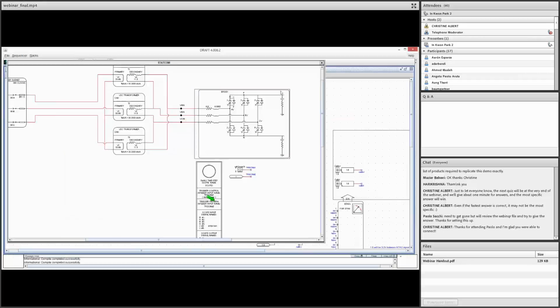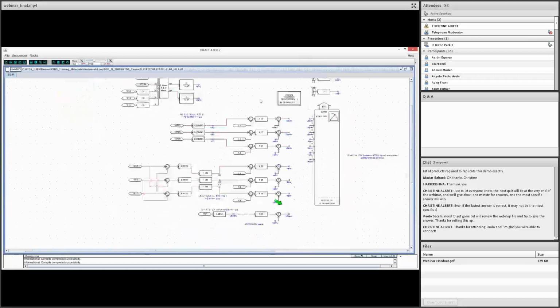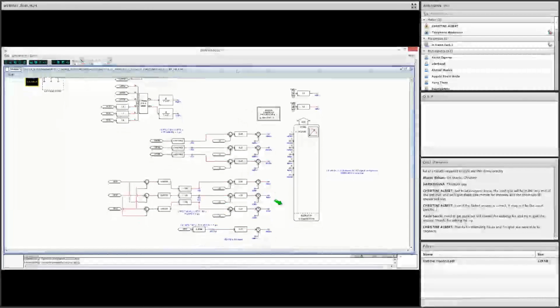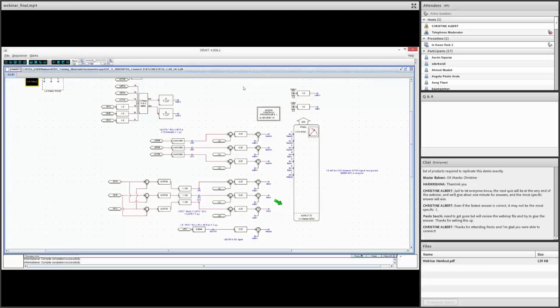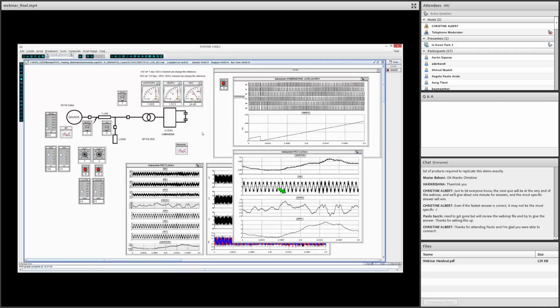And here, as I explained, are all the signal conditioning control blocks. The input voltage range of your DSP, the Texas Instruments DSP, is from 0 volts to the VCC. VCC is usually 3.3 volts. And the kit doesn't have any extra signal conditioning circuit. That means by using the signal conditioning, we need to make sure that the signal coming from the RTDS is in the same range as required by the AD converter. That's the reason why we have a signal conditioning circuit as a part of our simulation case.